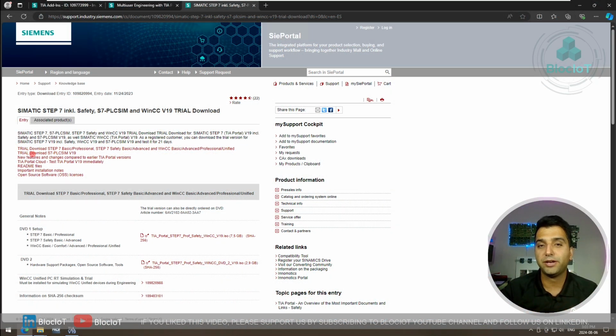Okay, let's get started, and in a real-life application, let's see how we can track the changes of our TIA Portal project. Our project will include one PLC, an HMI, or any other device that you might need in your project. So the first step to get started is to install the project server.